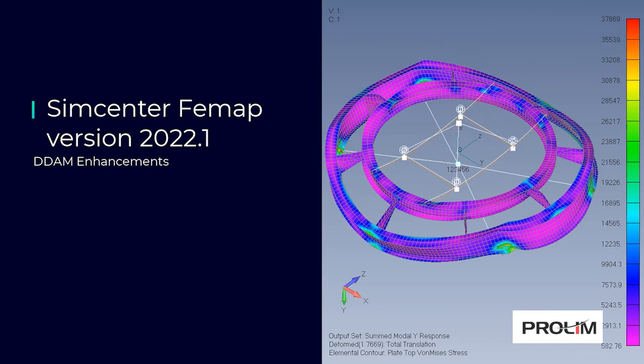Next, the Naval Shock Analysis Fortran program, NavShock, uses the modal effective masses and natural frequencies calculated by Nastran, along with user inputs, to compute shock design accelerations. Finally, Simcenter Nastran uses the shock design accelerations along with the modal participation factors and natural frequencies to compute the shock response of the structure.